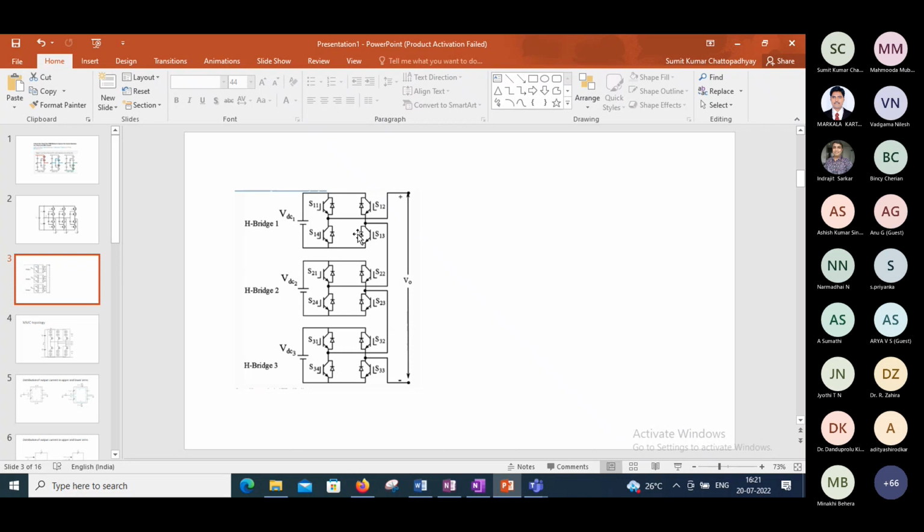Again, with the cascaded H-bridge, we can see that the battery bank can be distributed, and this can have application in many places, starting from traction propulsion, definitely propulsion, it has been proven. The multi-level, high resolution multi-level converter has made its path already. And other than optimizing the conduction loss in this way, having low voltage cells realized with low voltage MOSFETs,